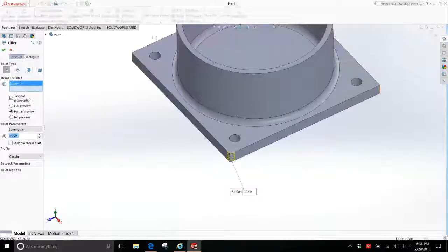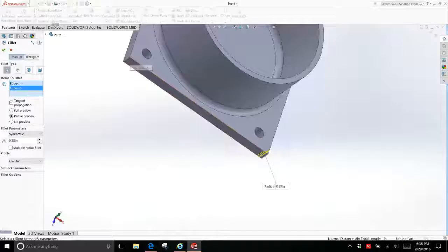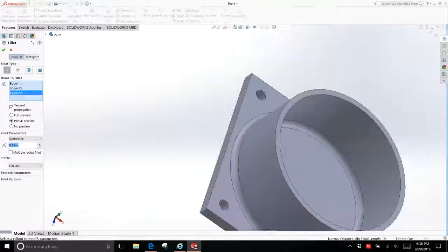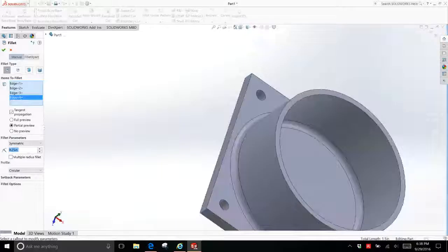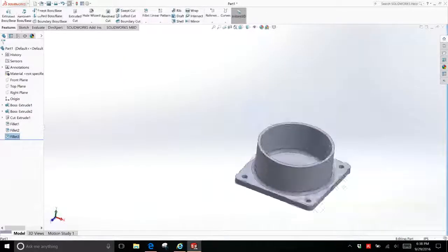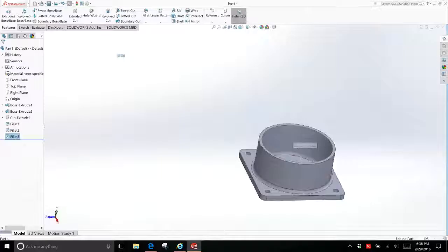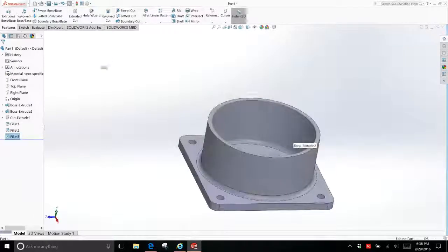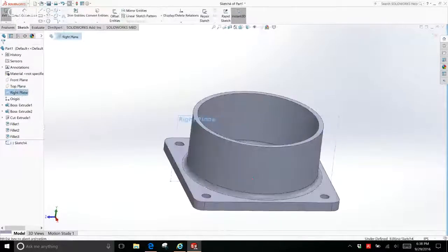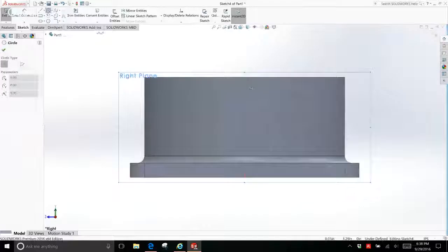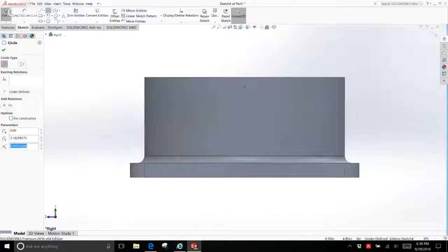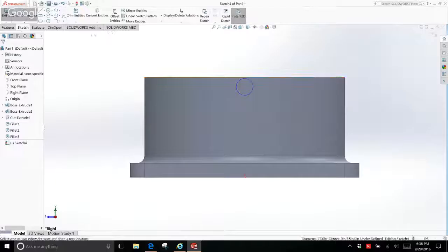And again, I'm not doing this from any sketch. I'm just pulling this out of my head as we go along. So if you can imagine with me just a circular pump, something that will pump water or something else, will just slot right down into there, and we can have a set screw on the side. Let's say maybe from the right plane. I can have a set screw or something like that. So we lock this pump in place using a set screw that goes in the side.